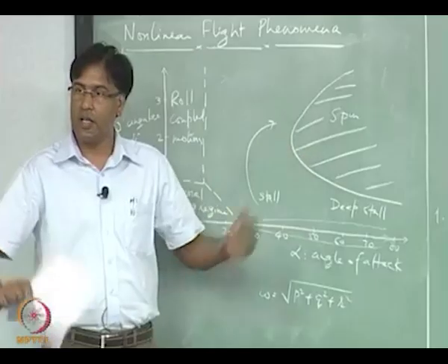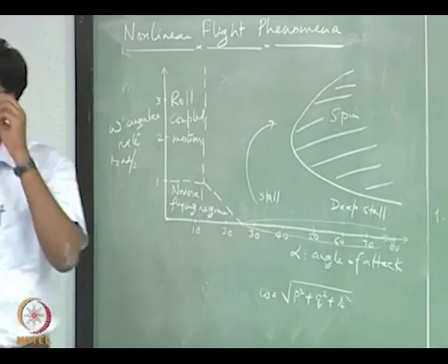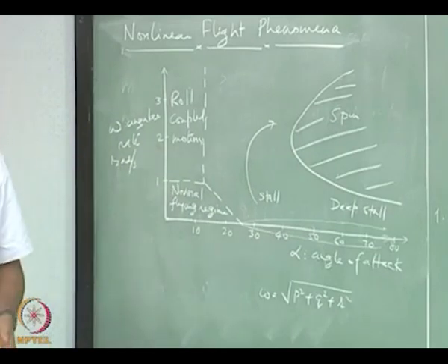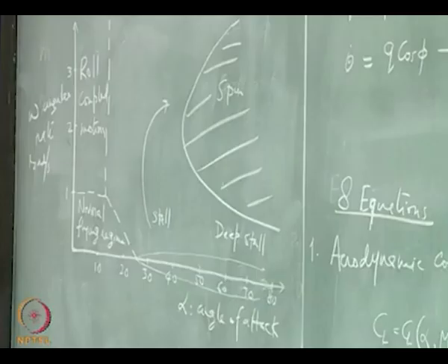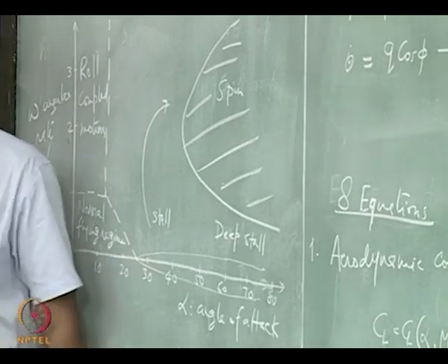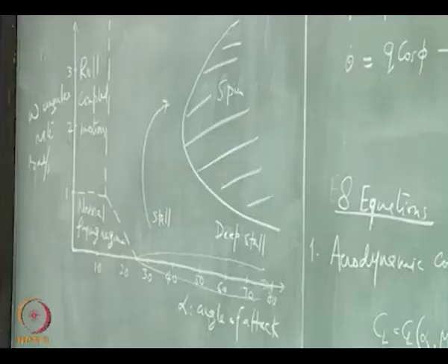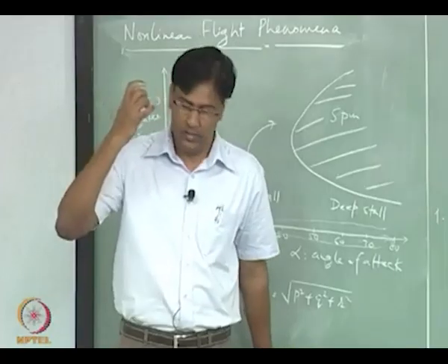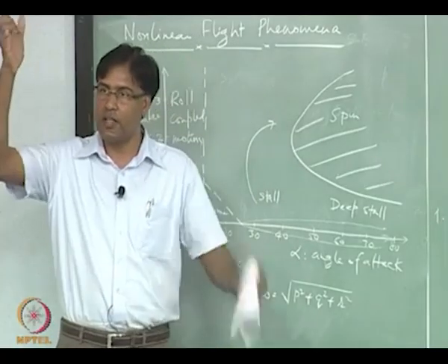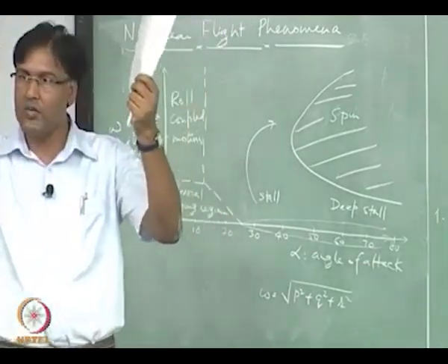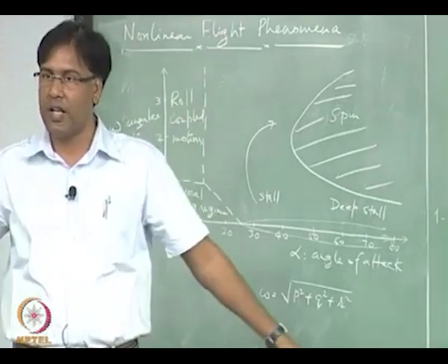Spin is an aerodynamic phenomenon. So it happens because you have taken your aircraft, or you have increased your aircraft angle of attack. Either you do it yourself, or it may so happen that you have a lot of wind, like a thunderbolt or microburst condition, where the vertical column of wind is coming down and spreading.